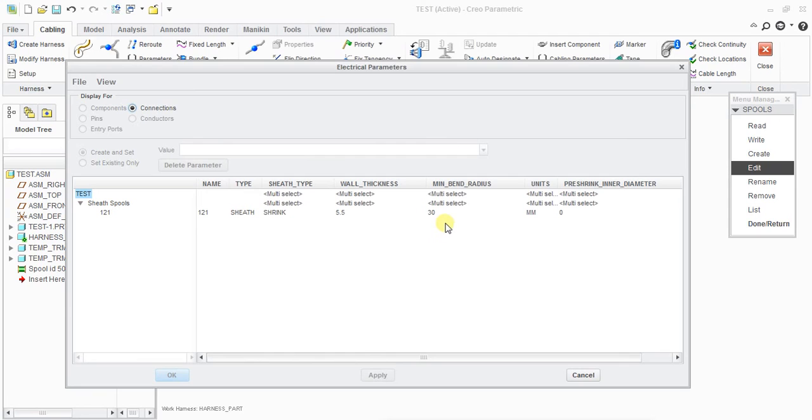And how do you calculate the minimum bend radius? Whenever there is a wall thickness, like 6, 10, 12, 20, whatever you are taking, you need to double it. Suppose here I am taking 10; wall thickness 10 into 2, so a minimum bend radius of 20 will come.